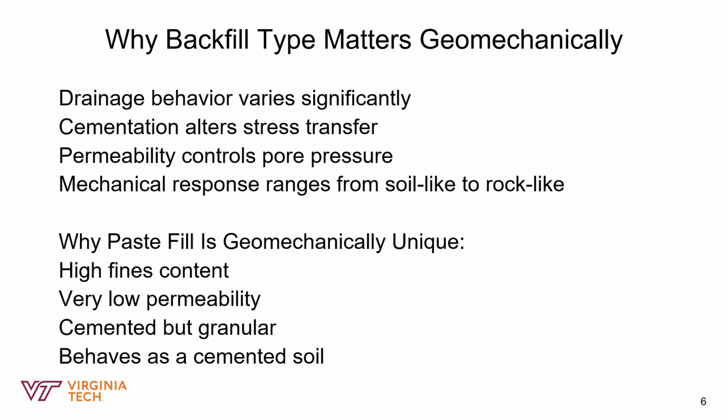So it's good to know what material you are dealing with, so you know how water passes through it. Also, we have the cementation. Adding binder changes how the stress moves through the material. And also the mechanical response, where the behavior can range from a loose soil to a hard rock.